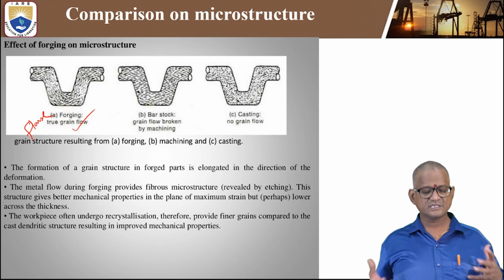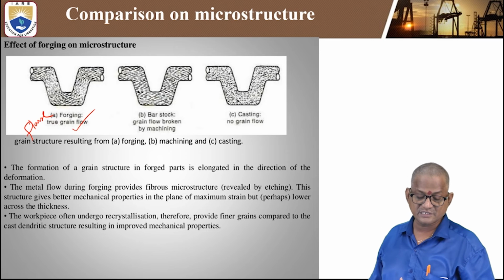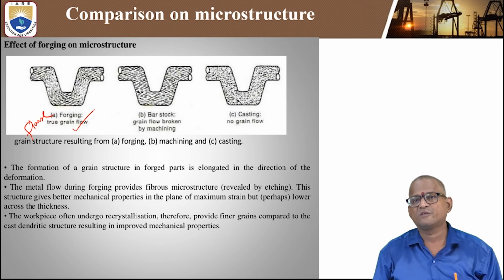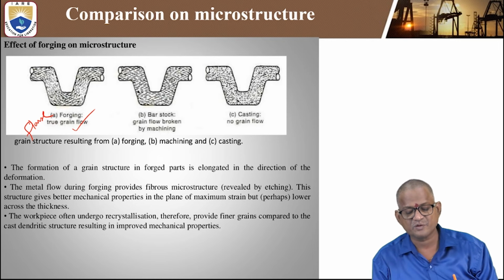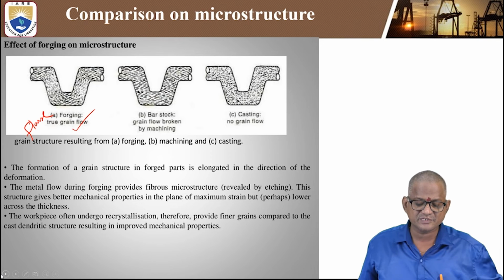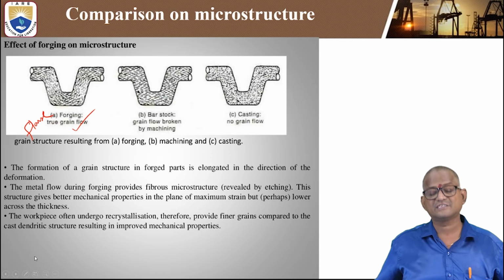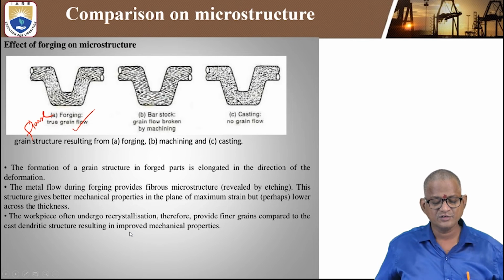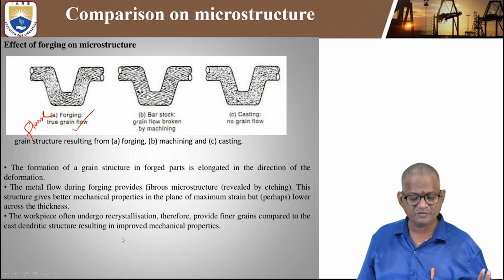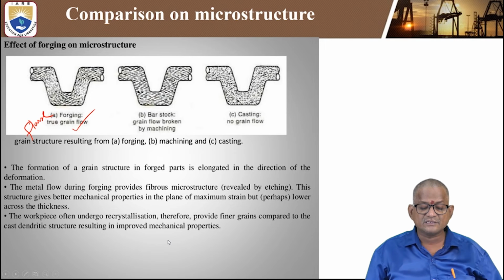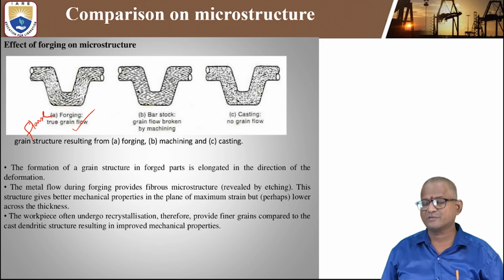Okay, this structure gives better mechanical properties such as mechanical strength, in the plane of maximum strain but lower across the thickness. And finally, the workpiece undergoes recrystallization, therefore providing fine grains compared to the dendritic structure, resulting in improved mechanical properties.